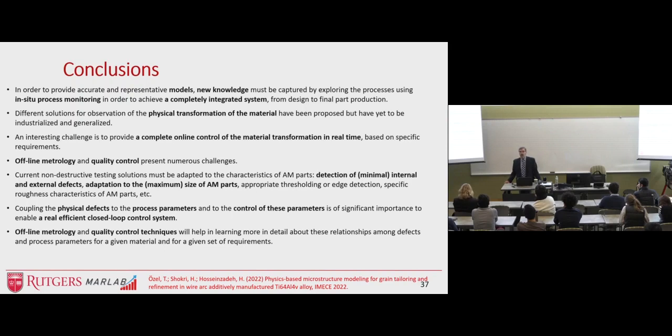If you can predict the onset of those defects, you can mark and record it in the virtual metrology tool. They actually happen randomly, stochastically, and their sizes can be affected by the laser process parameters. Then they can implement this into the machine as a virtual metrology tool. This is in practice in semiconductor manufacturing. They don't inspect every wafer, so you cannot inspect every layer that you fabricate either. It's an open problem with no answer yet, but it's a great research opportunity.